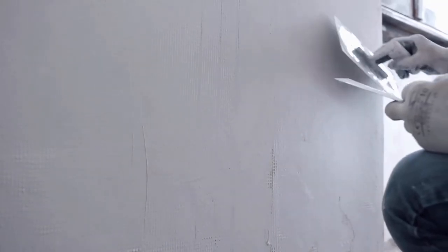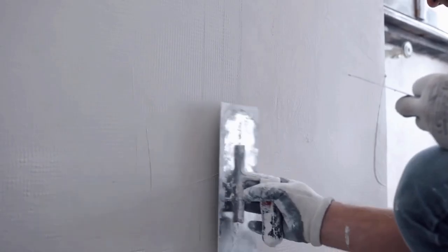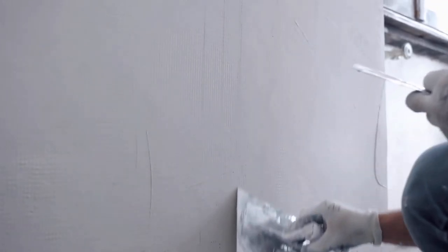And application: apply the plaster with a steel trowel in even thickness, level with an aluminium straight edge. Do not retemper the material after initial setting. So within the initial setting time you need to apply the gypsum plaster and complete the work. And finishing: final finishing with a trowel or sponge after 10 to 15 minutes. No water curing is required. That is a main advantage of gypsum plaster, you don't need any water curing. In cement plaster, water curing is important, otherwise cracks will generate. But in gypsum plaster, no water curing is required.